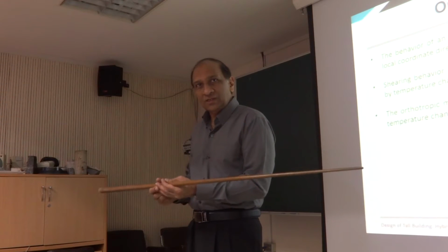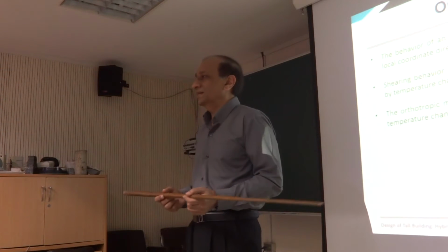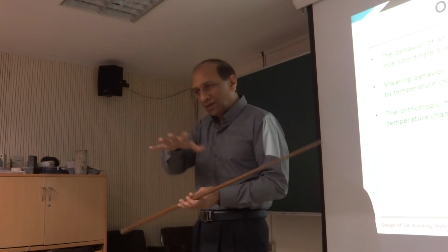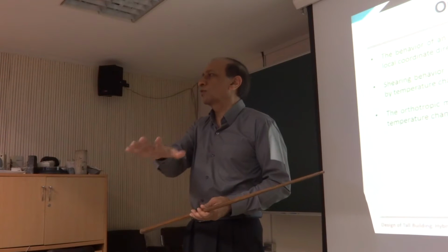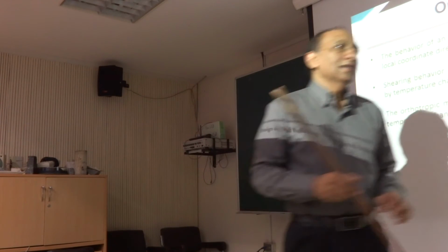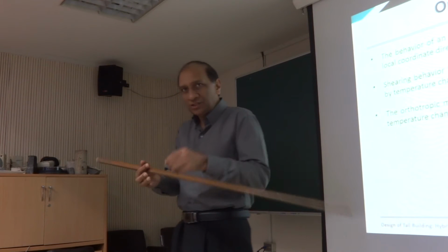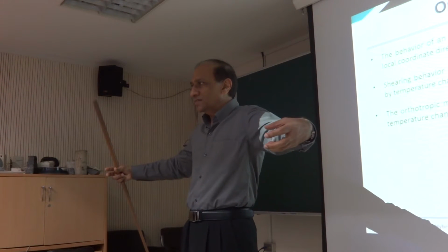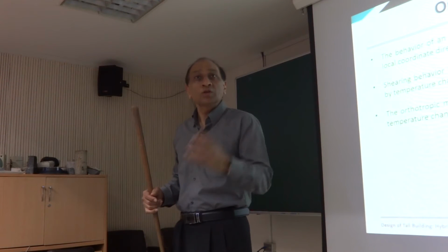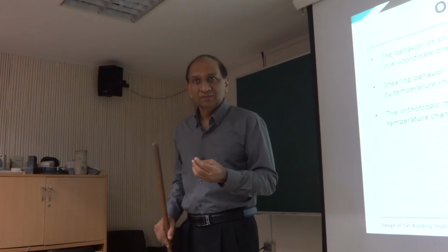So in one direction its properties will be different than in the other direction, right? Just to give you a very simple idea. So if you model that slab as isotropic, you are wrong because you are ignoring the difference in properties. Similarly, hollow core slab, for example, in the direction of the cores, different, other direction, different. Precast panel slab, totally different. So it's also the way material is used, right?